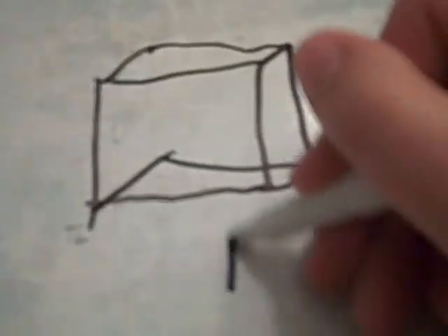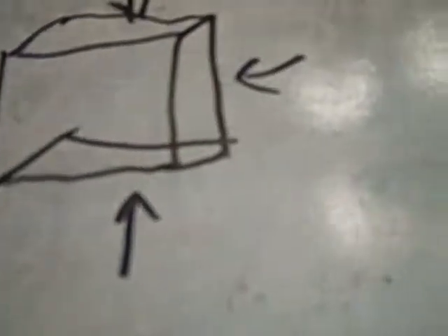So I have to account for every external wall in the house, which if there's none given, we assume 4, and the flooring and the ceiling. So the R10s of every surface that would touch the outside. So in this case, I would have 6 surfaces that would touch the outside, giving it an R value of 60.